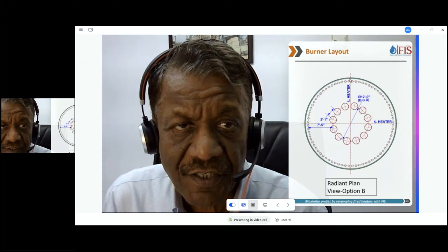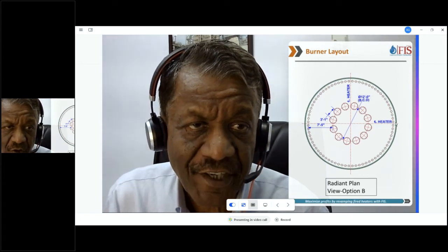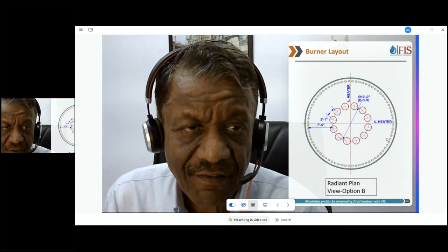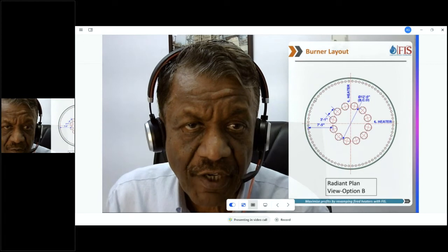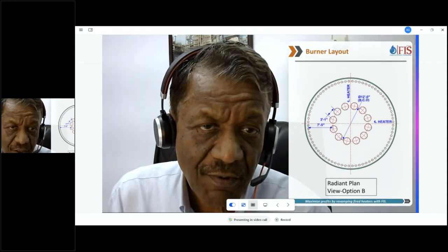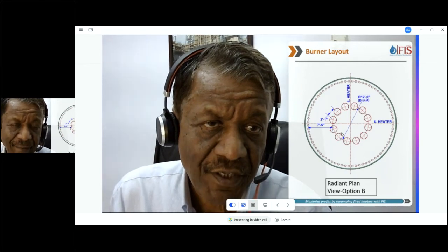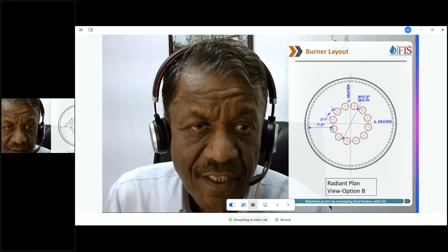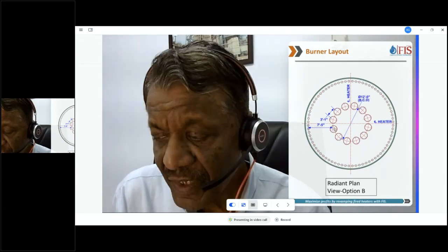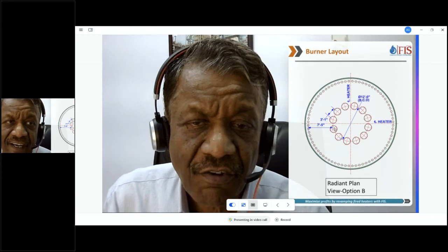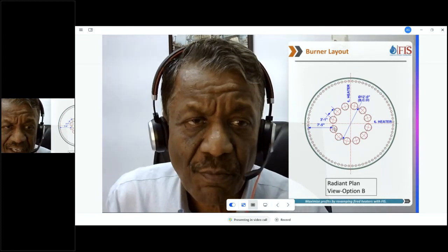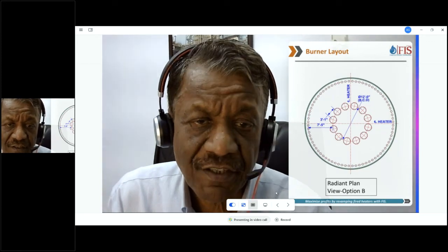This is the outer circumference of the heater, the wall. Then we have the refractory lining, and we have the tubes, 84 tubes over here, and then 12 burners over here. We came up with a 12-foot burner circle diameter. The distance between burner to tube is 7 foot 5 inches. So we are very generous in terms of clearances. So we give a very good, robust heater design for this service.